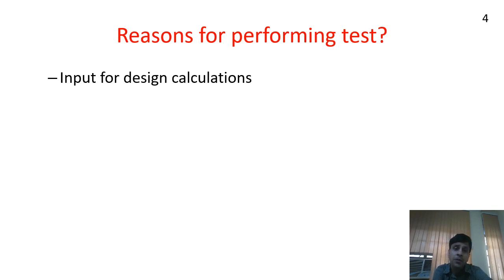It could also be input for design calculations. So let's say you want to use the rule of mixtures, and to use the rule of mixtures, you need the properties of the fiber and the matrix. For that, we have to perform a test.